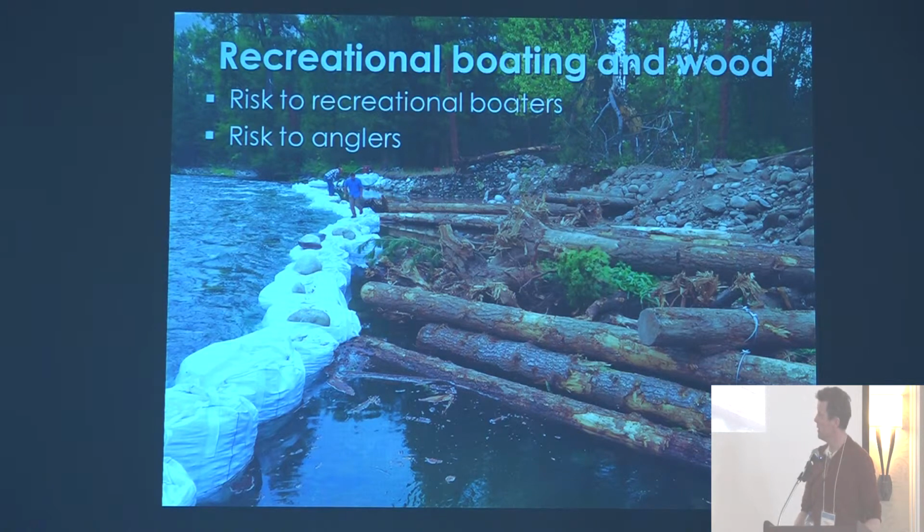So they're just a temporary, not a dewatering mechanism, but you just use usually gravel or material that's on site if you're excavating, or if you're not, you have to bring in sand or something like that. But they're 4x4 usually. I think they make 5x5 bags too. And then you can just move them around with the excavator, build a little coffer dam, and separate your work area. You can use them for dewatering. You just have to drape them with Visqueen or some kind of material that actually separates the flow out completely.